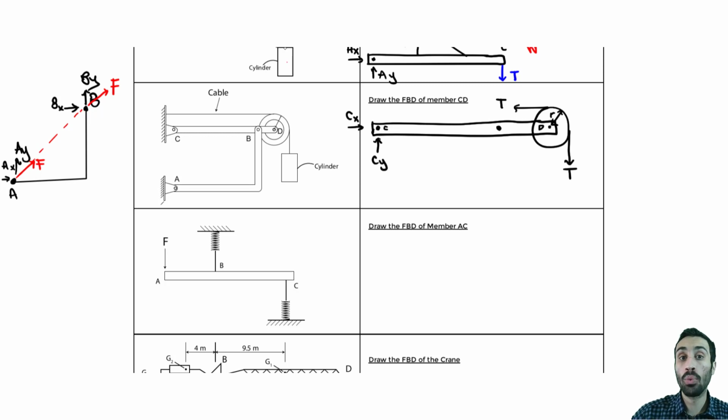And it wouldn't be a two-force member if you had an applied load hitting this thing, so it no longer becomes a two-force member. So always look for those two-force members only loaded at the ends, right? In this case at A and B, you have those reactions at A and B. So what does that mean? We know it's a two-force member, and what you can simply do is simplify this and draw the force like this. You can assume the direction and draw the force like that, right?